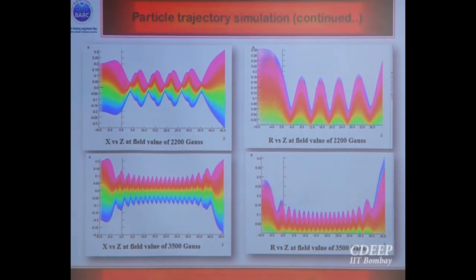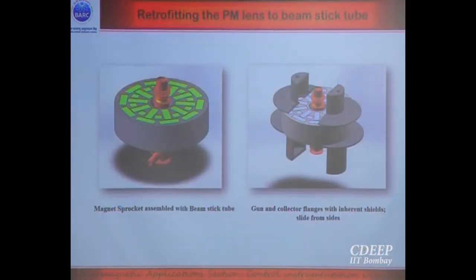So suppose 65 to 75% of the beam filling factor is required. We can calculate from that what the beam size entering at the cathode gun region should be, and the field level required in the RF cavity region. This is just after electrostatic and electromagnetic design. Then, by solid modeling, we try to integrate the components and plan how we will assemble them with the tube, because this tube is very delicate, having ceramic seals, and any mishandling during assembly can damage the tube totally.